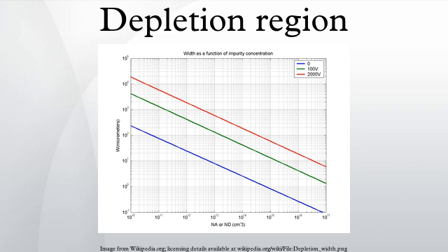A full derivation for the depletion width is presented in reference. This derivation is based on solving the Poisson equation in one dimension, the dimension normal to the metallurgical junction. The electric field is zero outside of the depletion width and therefore Gauss's law implies that the charge density in each region balance as shown by the first equation in this subsection. Treating each region separately and substituting the charge density for each region into the Poisson equation eventually leads to a result for the depletion width.